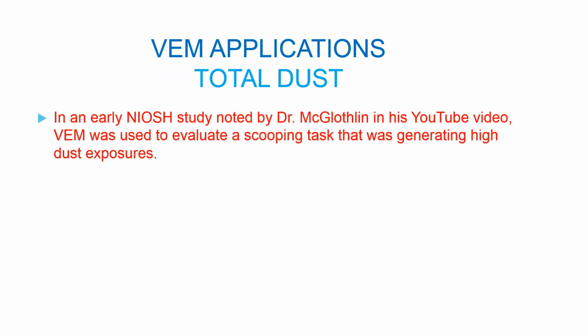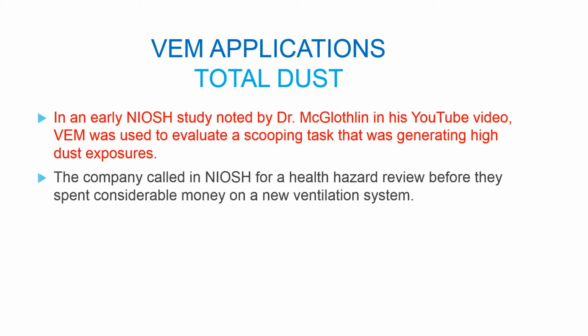In the YouTube video by Dr. McLaughlin, he shows an early NIOSH health hazard evaluation at a company that was experiencing high dust levels from the scooping task. They called NIOSH in because they were getting ready to spend some serious money on a control system, basically a new ventilation system, because what they had wasn't working.